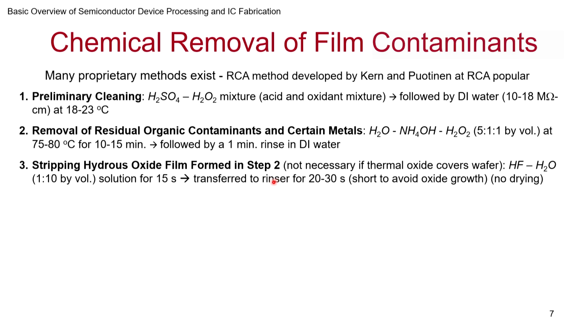Of course, in case there was already some oxide that was grown, a layer which contains oxide, then this step could be skipped, because you already have an oxide, you are just removing a small thin layer of the oxide on the top, so it may not be that useful. But this is a call one has to take. Sometimes removing a thin layer of oxide on the top may also be considered good, because it will remove any contaminant that is there along with that oxide that is going away.